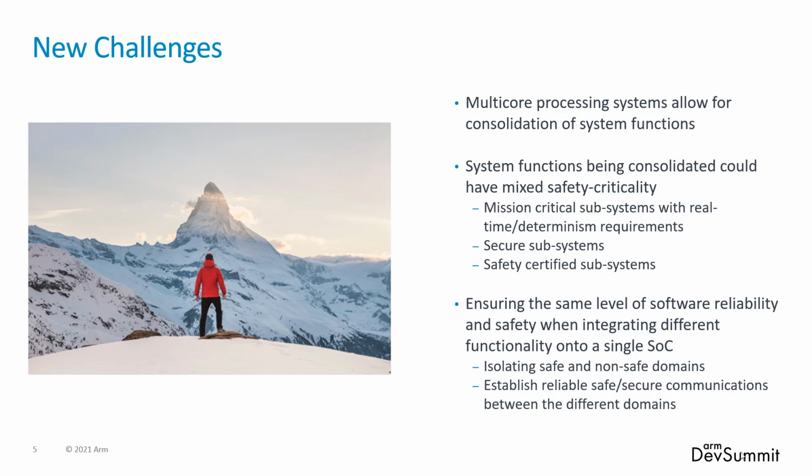With application cores and real-time cores, and in some realms, they actually call them safety islands, you can now start to consolidate systems that are not just of the same criticality, but of mixed criticality. In this case, I'm talking about mixed safety criticality, where maybe you have some functional safety functionality running on the real-time cores, but a general purpose operating system or non-safety on the application cores. Being able to leverage that opens up a whole lot more challenges, but also opportunities.